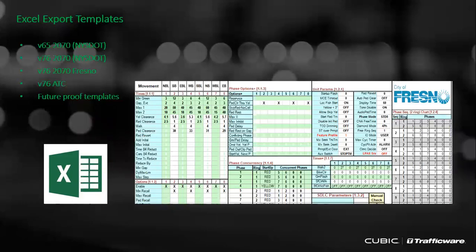And why was it causing issues? Every time a controller software is modified, new parameters are added, new options are added, and the list of those parameters shifts. If enough parameters are added, that list may shift just enough that the parameter you're looking for comes outside of the range where you expect it to be.